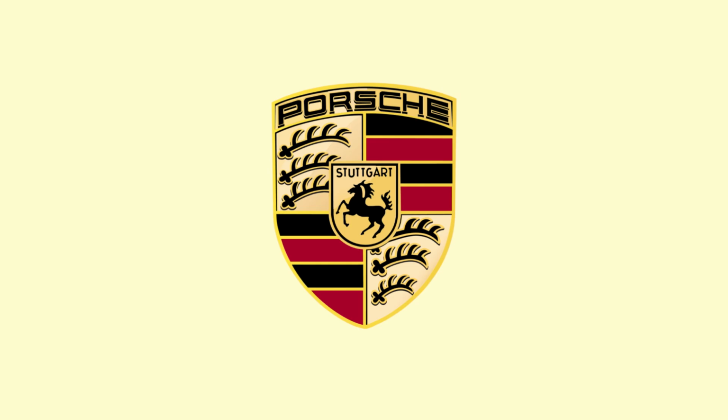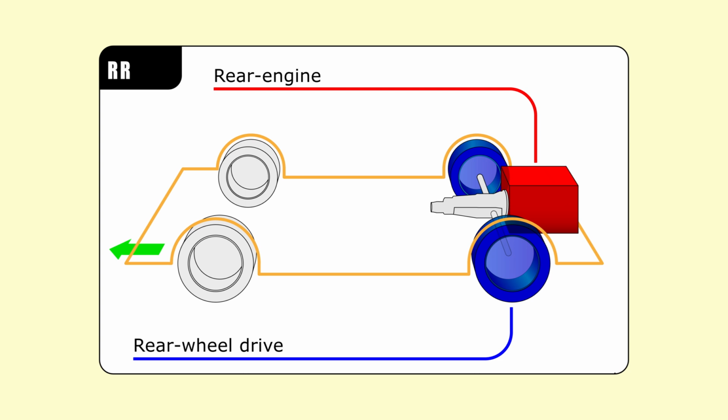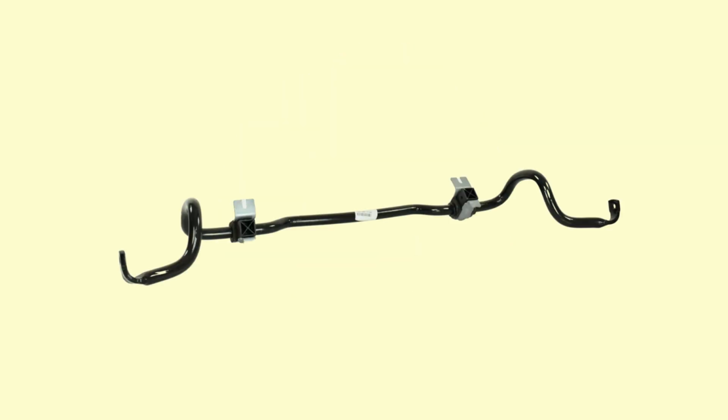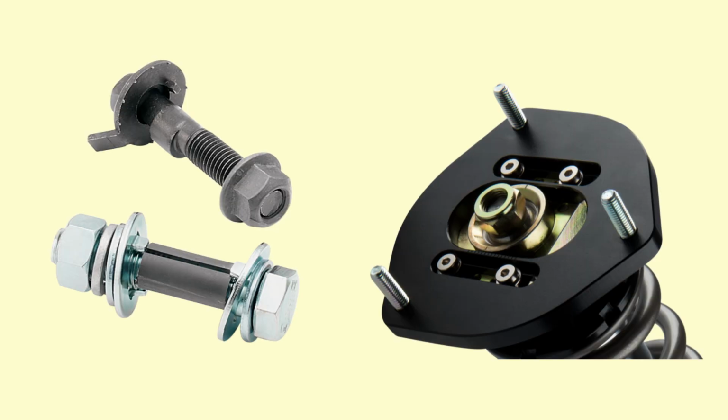A rare layout that's only used by Porsche nowadays, this is where the engine is situated between the rear axle and the rear bumper. This is known as the RR layout. This is essentially, in theory, a very oversteer-prone chassis and an exaggeration of the MR layout. However, even more decreased weight over the front wheels means, at times, RR cars can understeer out of a corner during acceleration. Similar to the MR layout, the same front aero enhancements can be applied, as well as previously mentioned modifications such as stickier tyres, stiffer front suspension, and a front anti-roll bar, as well as dialing in more negative camber to prevent snap oversteer.